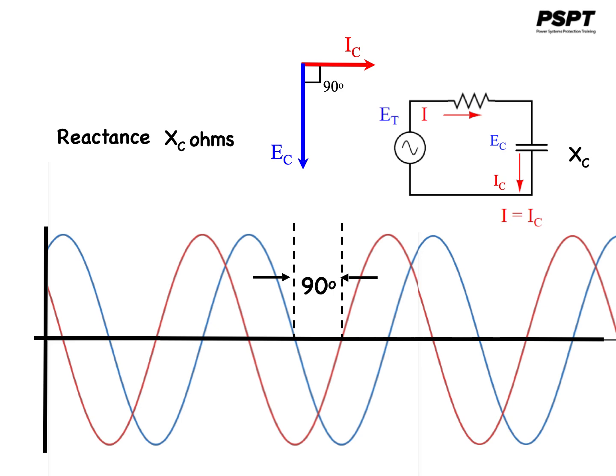We have already seen the relationship between the voltage drop across a capacitor and the current through it. That is, the voltage will lag the current by 90 degrees. A capacitor of a given size will impede AC current similar to the resistance of a resistor. That resistance is defined by Ohm's law to be proportional to the voltage across it divided by the current through it.